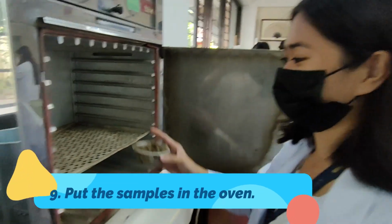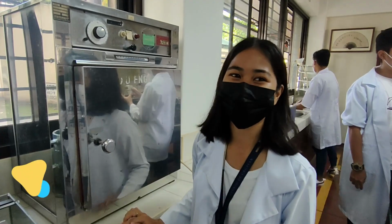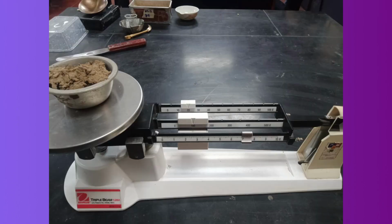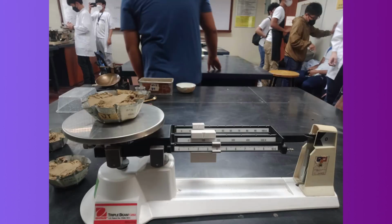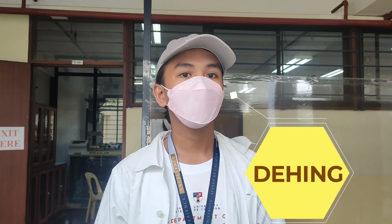Put the samples in the oven. After the samples are dried, determine the dried weight of the sample. After the samples are dried, determine the moisture content and liquid limit of the experiment.